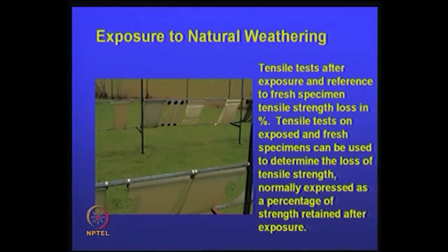As soon as he registers, take the piece and put it outside like this, which is what people have done in earlier cases also, or put it in the soil and then see its tensile strength and all that, because they give some information and we have to compare with what you test immediately. You get that material, you will have some number, say for example 40 kilonewton per meter, then you leave it for one week or 1 day or something, then what is the tensile strength.